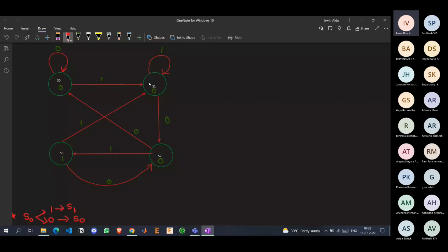After going to S1, if we give an input value of 0, it goes to S2. After reaching S2, again we give 1, and it reaches S3. This is our sequence path, or our correct path. See, our sequence is there, right? 1, 0, 1. It exactly matches the sequence we need to detect. So we have successfully broken the complex sequence into 4 separate states, or you can call it levels, however you want.